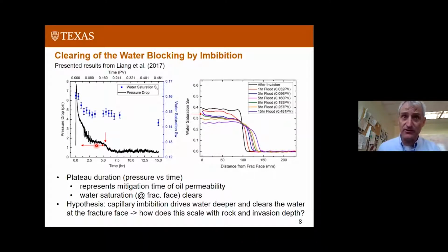But one thing we noticed, and Tianbo noticed this to begin with, is that when this plateau seems to end here, is exactly where we start finally clearing some water at the fracture face. So basically, this is a little bit of a capillary end effect that's keeping the water in. The hypothesis is a capillary end effect that's keeping the water in this little bit of the fracture face.